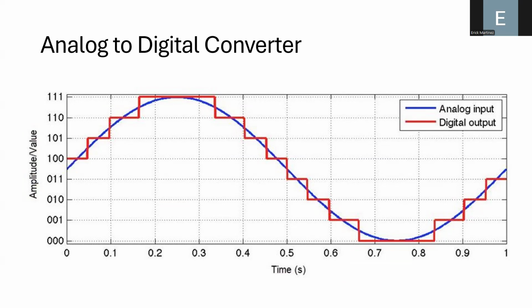In fact, you need particular processors to collect data effectively, and we call those real-time processors. A real-time processor is basically a computer that can take samples in a deterministic fashion. That is, if I program the device to take samples from the sensor every second, it will always obey that and always take one sample at every 1 second.